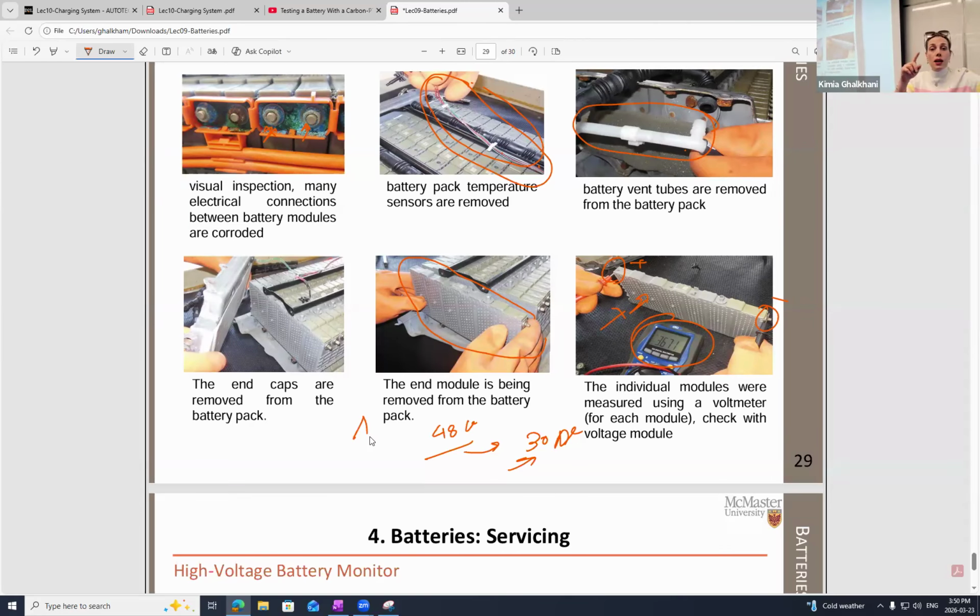One of my cells, because the cells were really heavy, while the technician was pushing them inside the case, they didn't care enough, and only a single scratch, even no leakage of the material, a single scratch on the surface of the battery removed the insulation of the surface, and that one had connection with the other batteries, causing this much self-discharge, almost 18 volts or something like that.